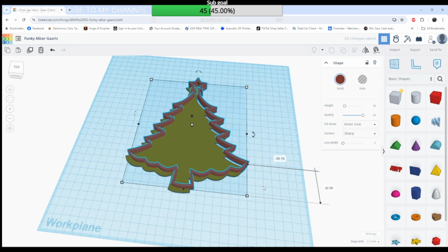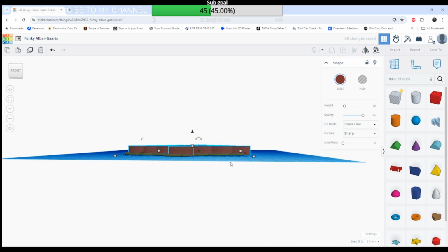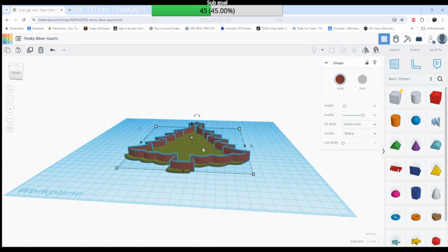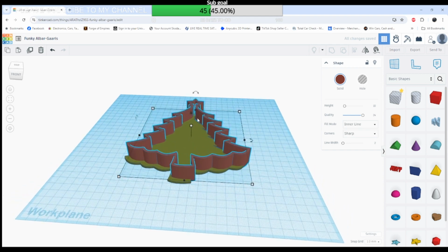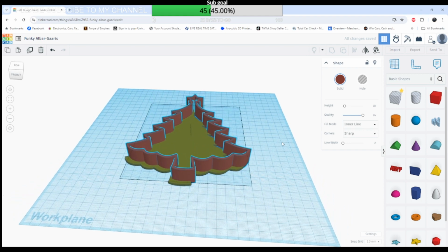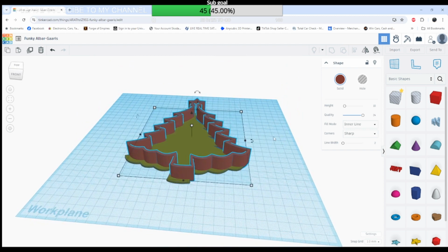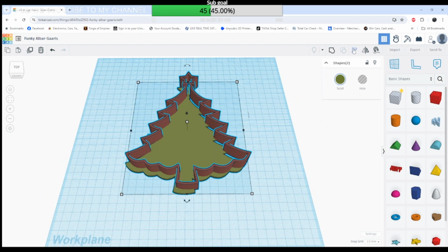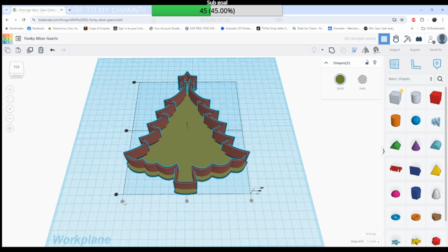And we'll have this lined up over here, but obviously this is the same thickness as that, which is okay because we've got 10 mil. I want that to be, say, 20 mil because we need to insert the LEDs on the inside. And we need to line that up now, so highlight both together, click this item up here, and then we can line these up.